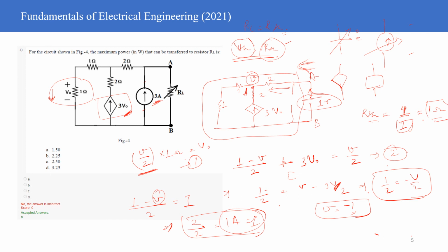Then let me figure out the Thevenin's equivalent voltage. For Thevenin's equivalent voltage, you open circuit the load and keep the rest of the circuit intact, except at the points where you want the equivalent voltage. So this branch is now open and everything else remains the same.